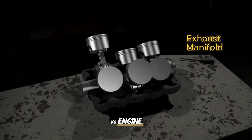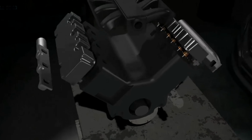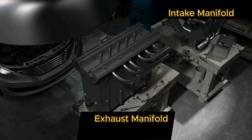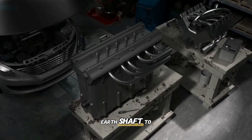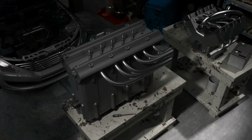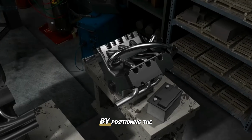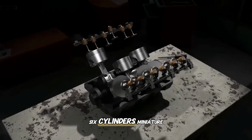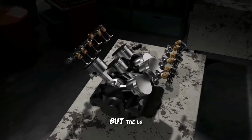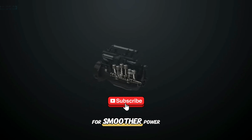This is a V6 engine. Cylinders are placed in the form of the letter V. When the number of cylinders increases, the length of the engine becomes longer. This will also cause the crankshaft and camshaft to become longer. Of course, the width of the car will also increase. This is why many car companies produce the V6 engine. By positioning the 6 cylinders in a compact configuration, it can reduce the length of the engine and the width of the car, but the L6 engine is much quieter than the V6 engine, and it allows for smoother power transmission.